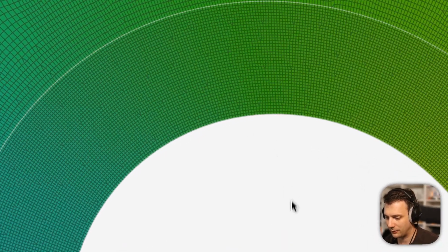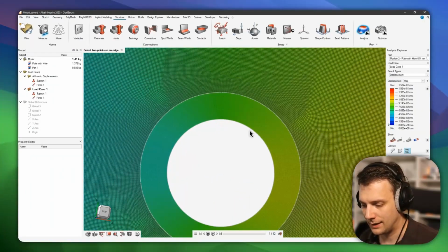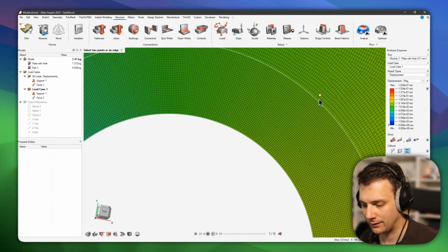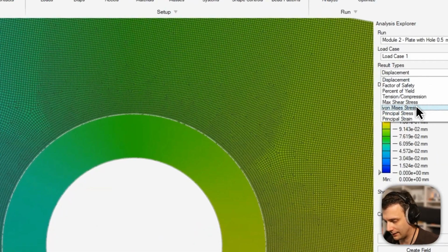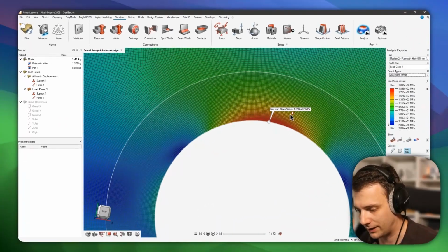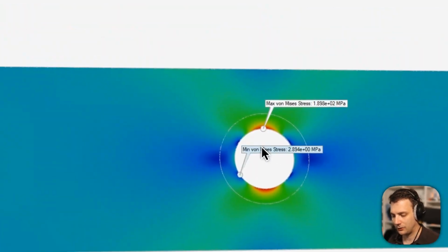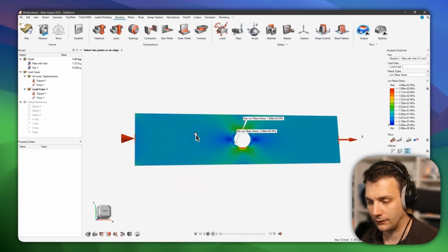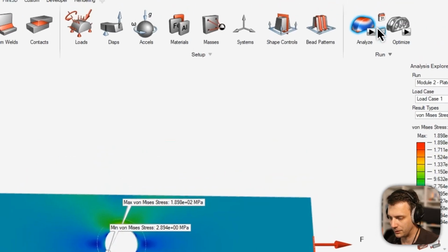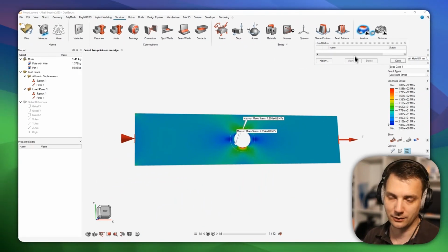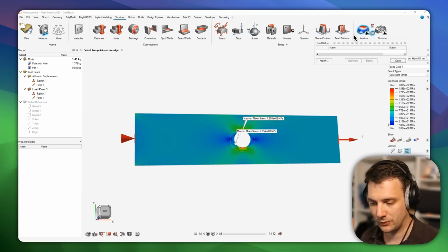Well, okay, for this example, it doesn't matter if it's the 0.25 or the 0.1 model, but you see the difference, right? It goes down here. It still has a lot of elements, but you can see then that the von Mises stress is a lot higher. Here was the 189 megapascals here, but you see there's a lot of elements, and it takes more time to compute those. So in this case, I think a couple of minutes. Still alright, but you can think of bigger models needing a lot more time to converge solutions like this.